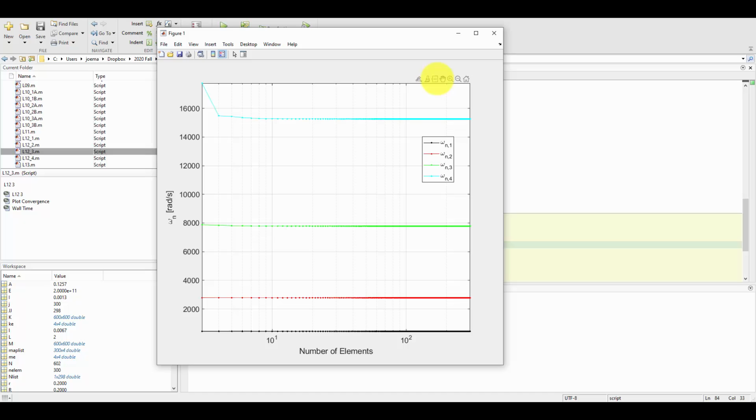So this was saying that the entire beam was the larger diameter, and we can see what the natural frequencies are for that beam. Again, we should not expect them necessarily to match the tapered beam, and in fact they don't in this case. We're getting that the smallest natural frequency is 444, and the largest is a little bit more than 15,000 radians per second, and then we get 2 in between. So certainly different than we got from treating it as a tapered beam in the finite element analysis.